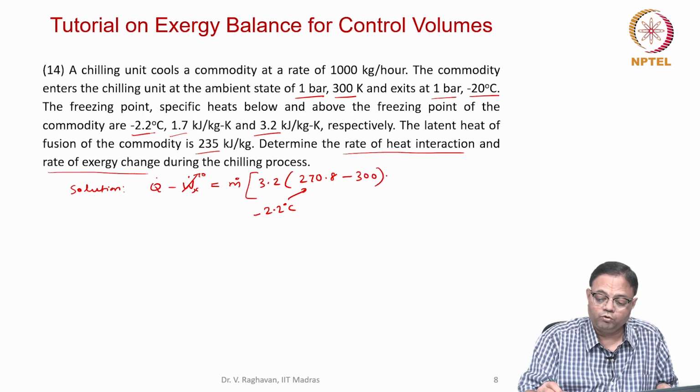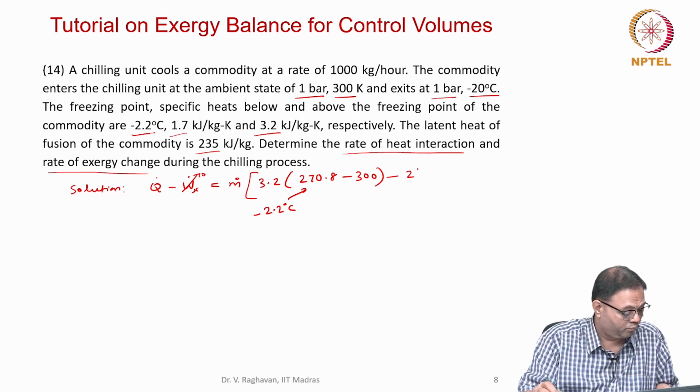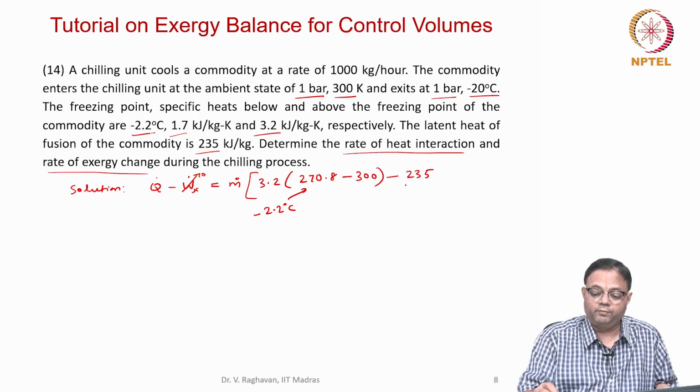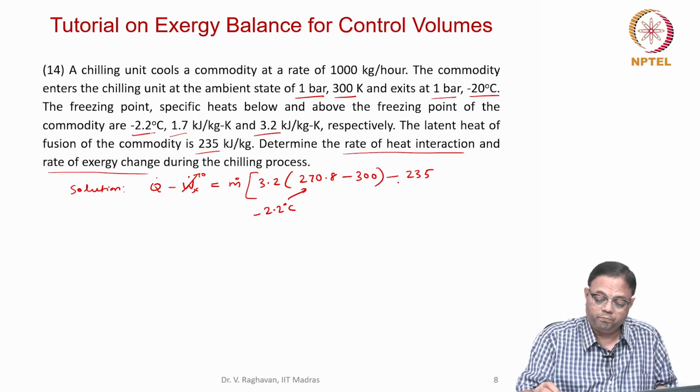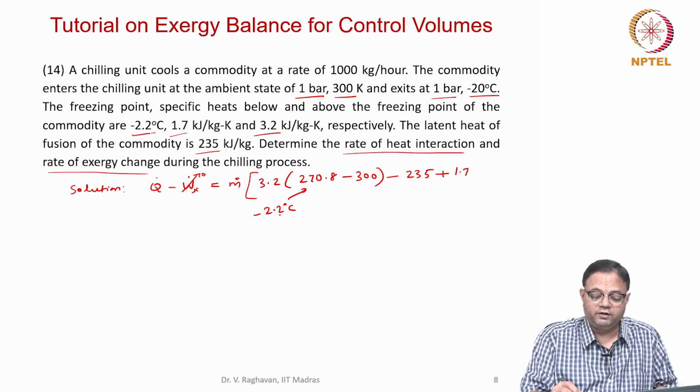Okay, now I have to remove the latent heat also. So, that also you put minus 235. Since I am removing, I have to put a negative sign here, plus 1.7. Now, it has reached the freezing point.